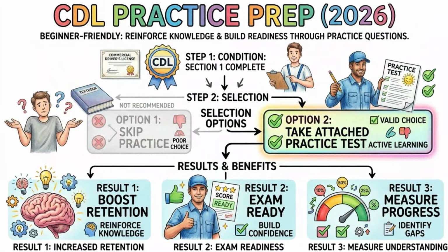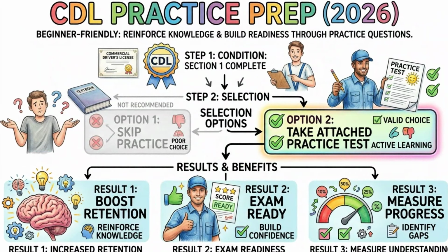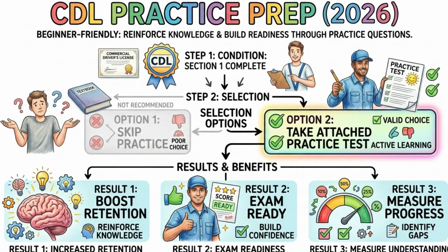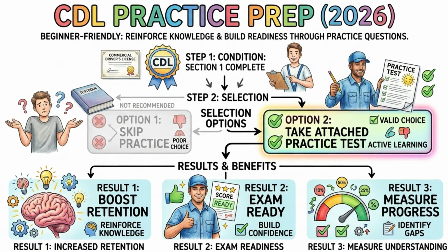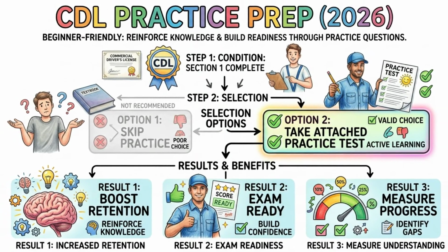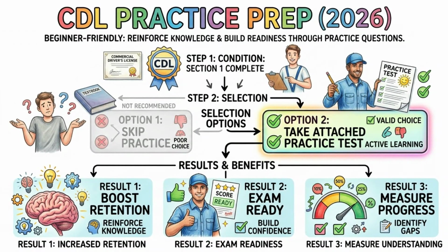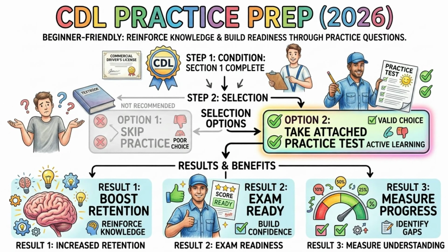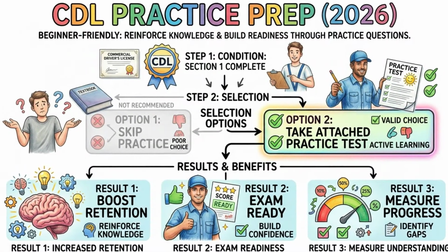The general knowledge test also evaluates your visual search skills and how well you manage your line of sight. As a commercial driver, you should be looking 12 to 15 seconds ahead of your vehicle at all times. At highway speeds, 12 to 15 seconds translates to about a quarter of a mile, or roughly 4 city blocks. Looking far ahead allows you to spot traffic jams, lane closures, or hazards with enough time to smoothly adjust your speed and change lanes. This specific 12 to 15 second rule is almost guaranteed to be on your permit test.